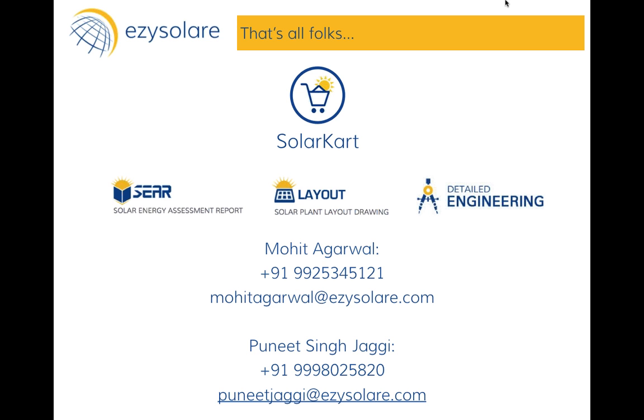Theoretically, it is very difficult to pinpoint the soiling loss, but what you can do is have a set of dirty panels that you do not wash for, say, 1 month, 2 months, 3 months, and a set of clean panels right adjoining it. You could measure the output of both of these panels and arrive at the soiling or dirt losses. So that's theoretically the way to do it. But otherwise, measuring it on a yearly basis becomes slightly difficult. At least I'm not aware. Probably there are people working on micro inverters who can eventually measure that also.